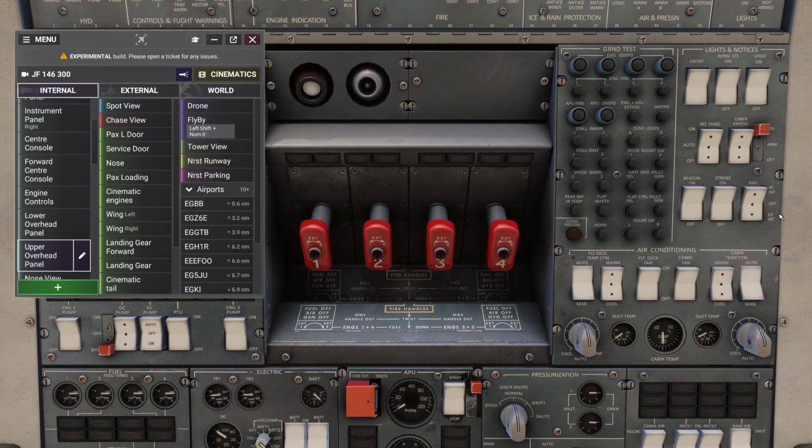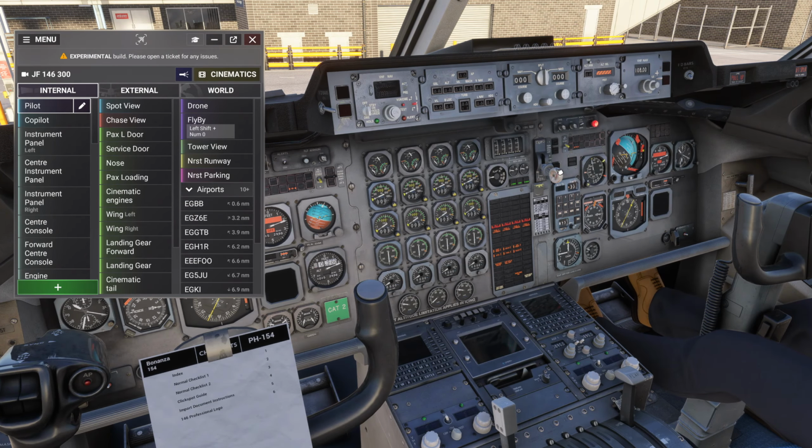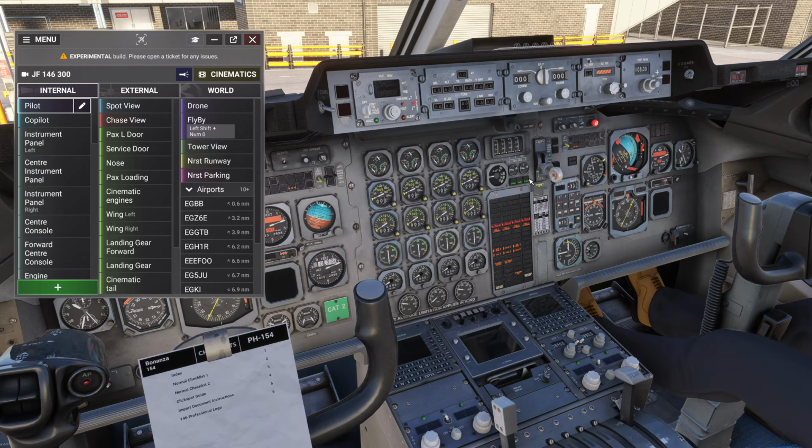Perfect. Next up, let's turn on the no smoking sign and arm the cabin emergency lights. Let me know once that's done, and we'll keep moving forward. No smoking lights on. Cabin emergency armed. Check. Awesome. That's great. Next, let's check the landing gear to make sure it's down and that we have all 3 greens showing. Once that's confirmed, we can proceed to the next item. Let me know when you're set. Landing gear is down and I see 3 green lights. Checked. Perfect. That's all set.